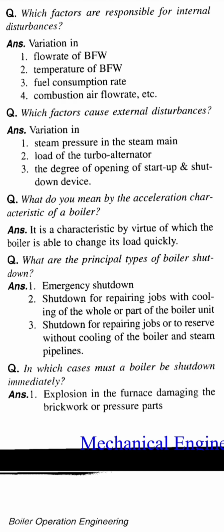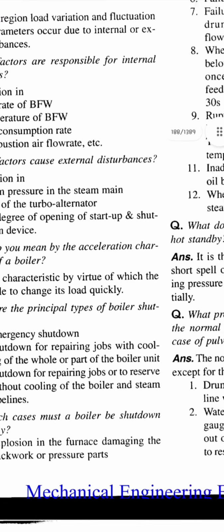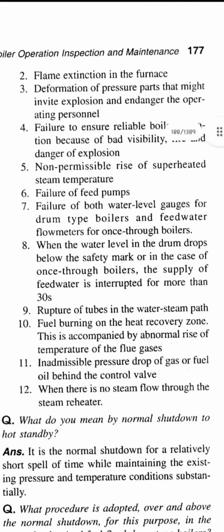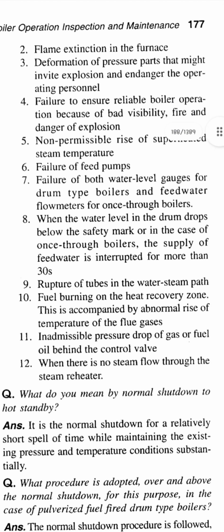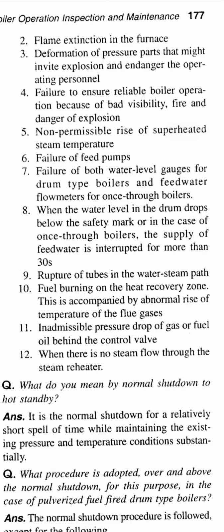Question: in which cases must a boiler be shut down immediately? Answer: explosion in the furnace damaging the brickwork or pressure parts, flame extinction in the furnace, deformation of pressure parts that might invite explosion and endanger the operating personnel, failure to ensure reliable boiler operation because of bad visibility, fire and danger of explosion,